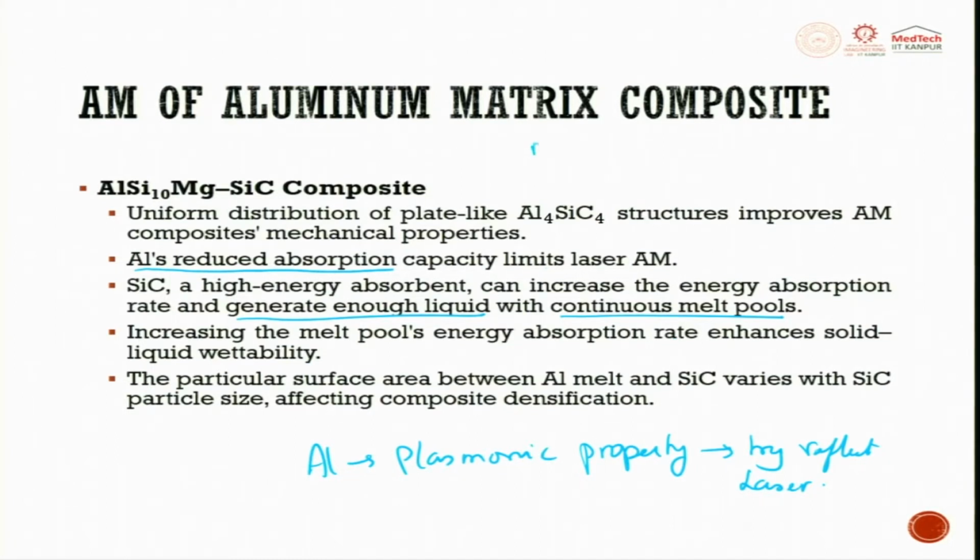When we are looking at all these MMCs, the wettability of the reinforcement with the matrix is very important. If the wettability is not good, then you will not have an interfacial bond. If the interfacial bond is not there, interfacial strength will not be there. If the strength is not there, then the particulates will get dislodged very fast when you try to put it into real-time use.